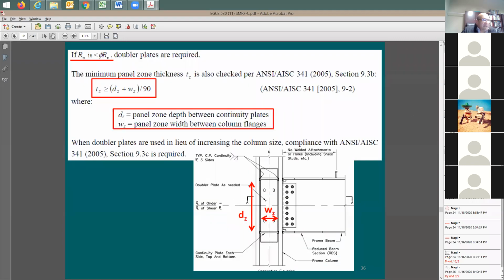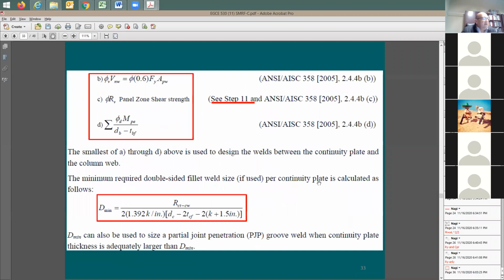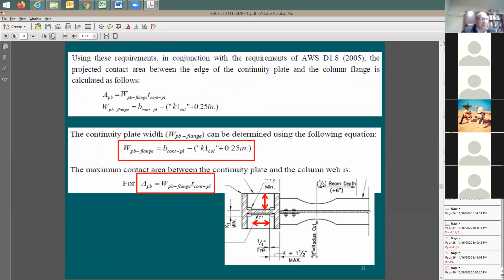This is going to be the continuity plate. You see this plate? This is a small plate. You have top, both sides of the column. You have also at the bottom, both sides of the column. So why are you trying to put here this continuity plate? I'm going to say because if I'm going to put here any tension force, right? This tension force is going to be going throughout the width of the beam and again get transferred to the column flange. Like in plan view, if you like to see it, I'm going to go back here, right? I'm going to be looking at this continuity plate, meaning that you're going to be putting here some stresses. It's going to be coming this way, right? Like some tension force is going to be distributed because it's going to be coming from the beam flange to the column flange, right?